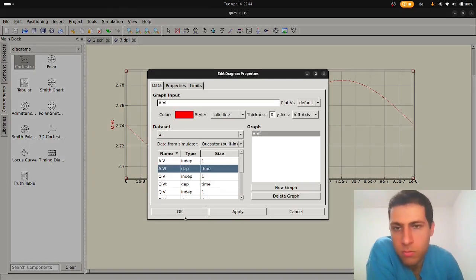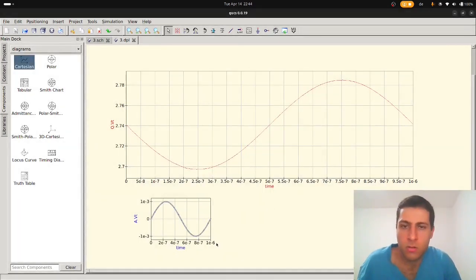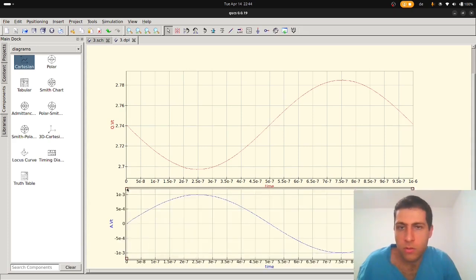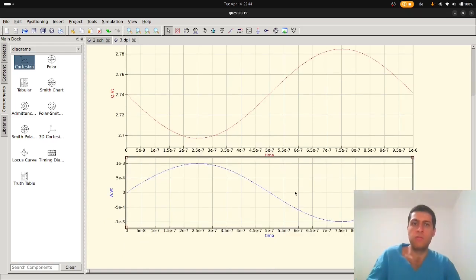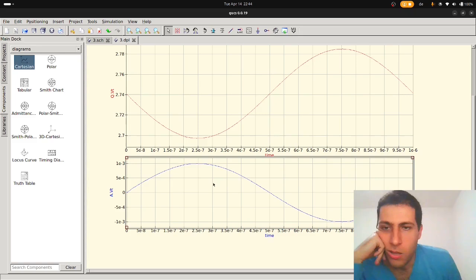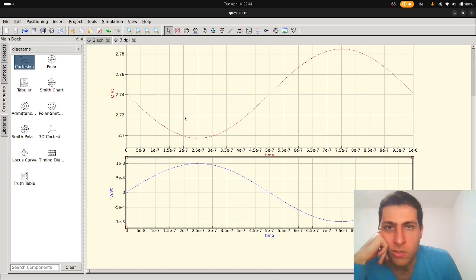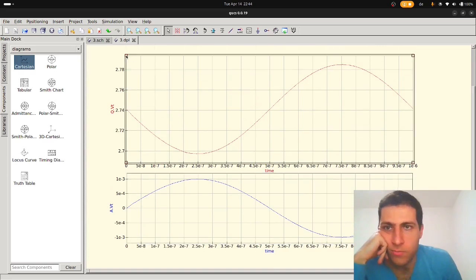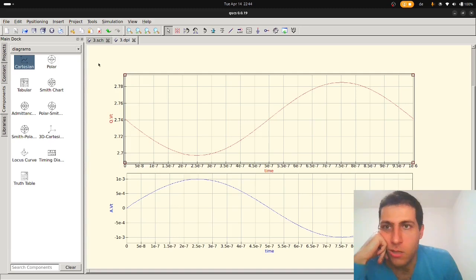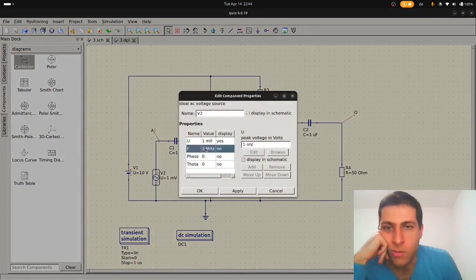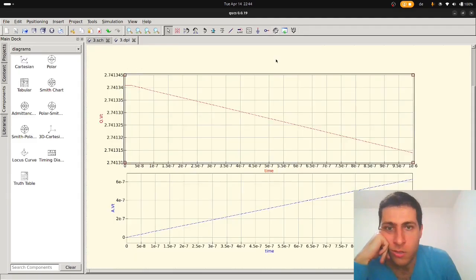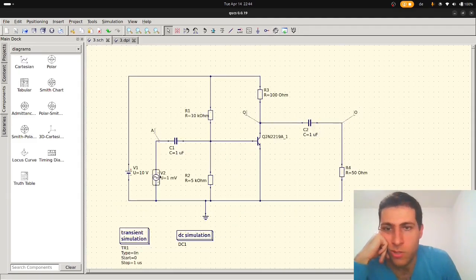So it is 10 megahertz, which is well above the pole and zero. And there's a slight difference in phase. There's a slight shift in phase, and if I turn this 1 megahertz into 1 kilohertz or even less, then for example 100 hertz, then this becomes a huge phase shift.